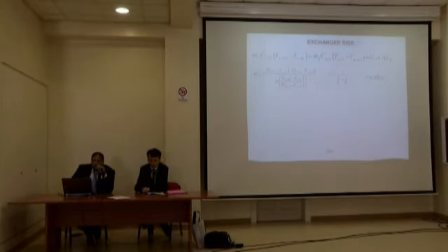This helps us to relate the mass flow rate of fuel to the space heating load, Q dot heating, the heat of combustion QC, and the overall efficiency of the boiler eta B. This finally yields the mass flow rate of the exhaust gas of the boiler, m dot G, which is (A plus 1) m dot F, with A or AF the air to fuel ratio of combustion.